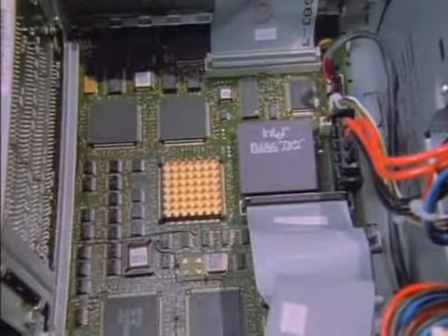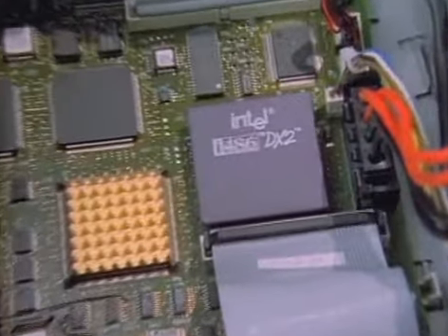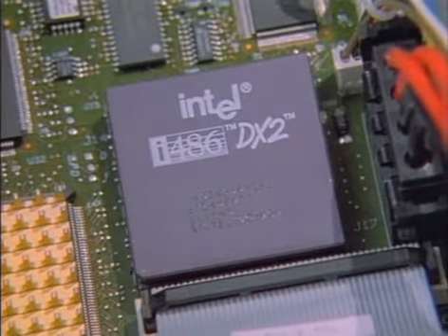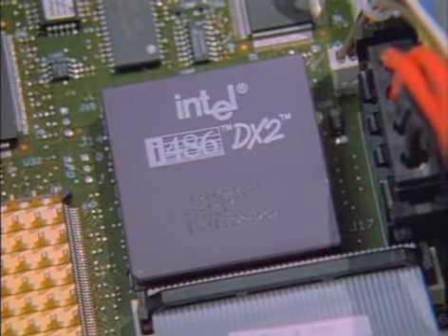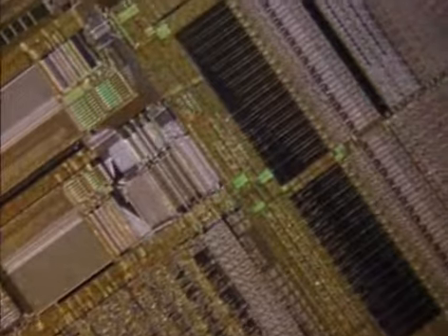Inside of this computer, you find a microprocessor containing over 1 million transistors. The speed of a signal traveling through these transistors affects the computer's performance. In an ideal environment where there is no resistance, an electrical signal would travel at the speed of light. In a chip, however, resistance from the conductive paths between transistors and the capacitance of wires and transistors slows the signal speed.